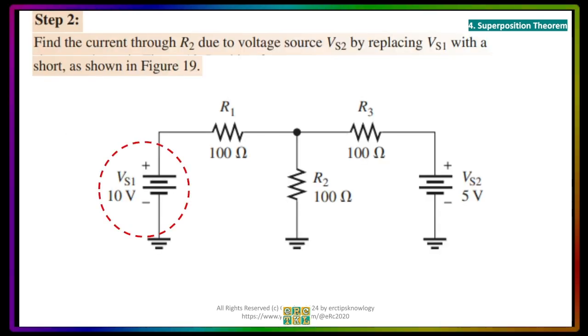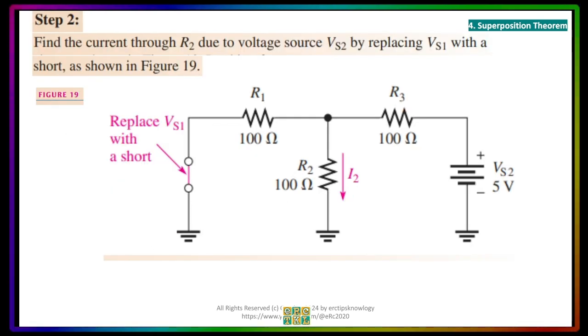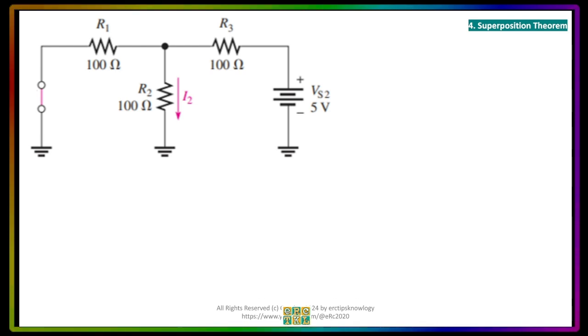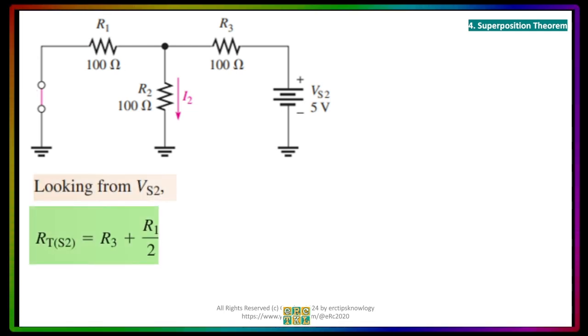But it does not mean that this is the final answer, because again, we have to consider shorting the source 1 now. This time, we replace source 1 with a shorted wire, and let's see what will happen. In the analysis, the voltage source 2 will be used as the source, and the I total now will go to I3 or R3. So I total with respect to source 2 is equal to the I3. And the parallel this time will be the R1 and the R2.